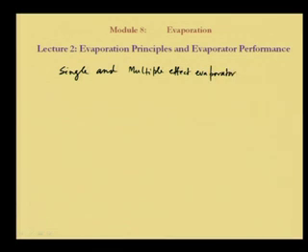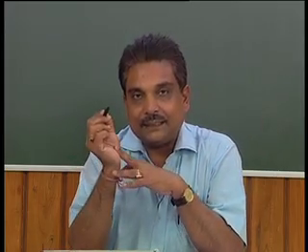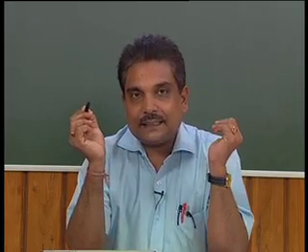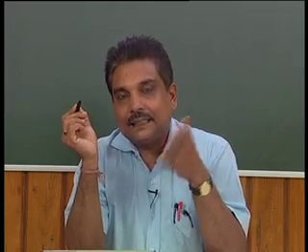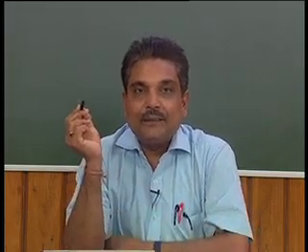Evaporator. So we have understood that an evaporator means there will be a liquid solution which will be heated up by a heating medium, normally condensing steam. What happens in that case is that it is evaporated and the thick liquor comes out. When all of this happens, it is called a single effect. Now, many times it need not be a single effect; there can be multiple effects.